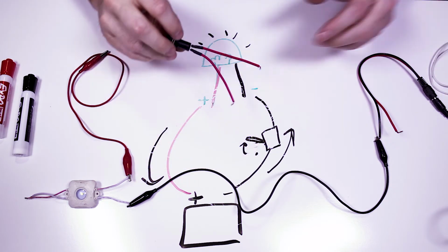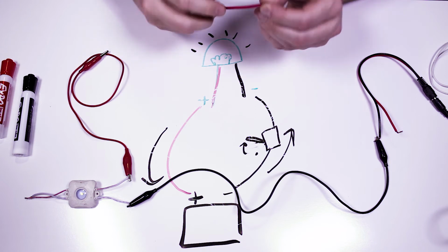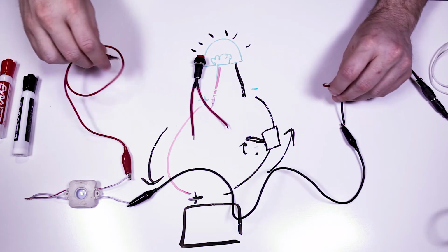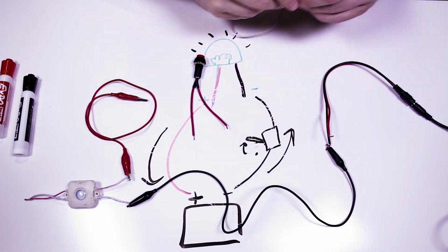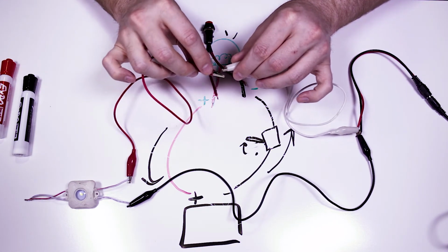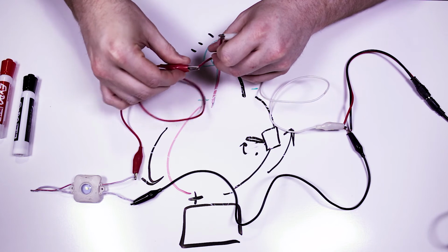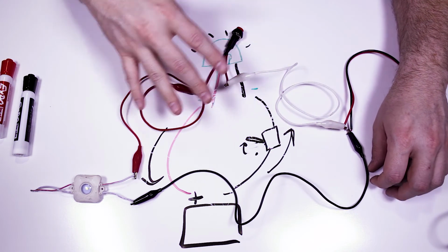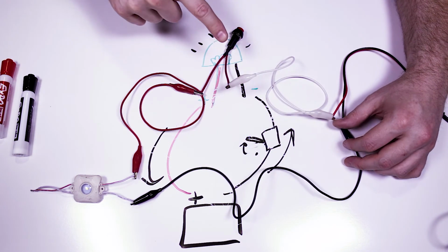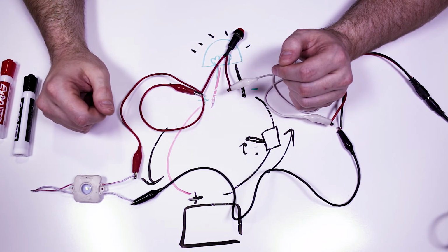Now, when you wire a switch into something, and I actually did this wrong here, I should have done it on the red side. It is good practice to wire up the switch interrupting the positive, right? So you just imagine that this switch is an extension of the positive rail here, like this. So what's going to happen is, instead of these being here to cause this to light up, I'm just going to put this here, like this. And the reason you want to put this on the positive is this means that no voltage is flowing through it at all. If you put it on the negative side here, you still have the chance of some electricity flowing in the circuit. If you do it like this, nothing's happening. At least that's what everybody has told me, and that's what I've read, so I'm assuming it's true.